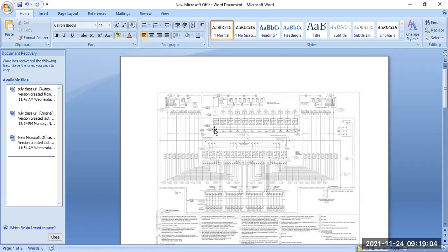One by one you have to check where the connections are going. After some time you can find the fault, then replace it or solve it, and the process starts again. In this way, we very frequently need maintenance, and this is our main target. That's why we have to know the panel diagram.